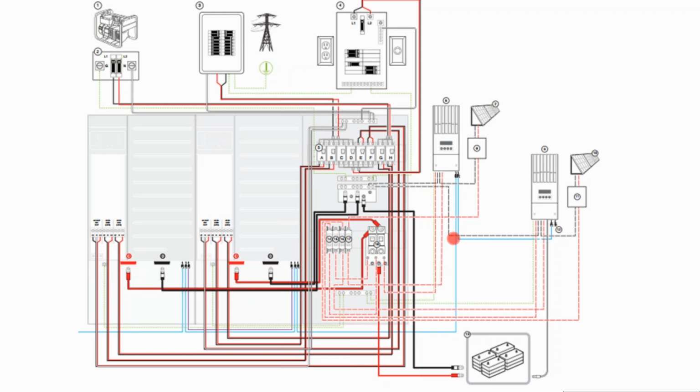This is because this particular system is a negatively grounded system, so the negative is connected to ground. If you had a floating system where the negative is not connected to ground, you would have to have breakers on this negative bus as well.